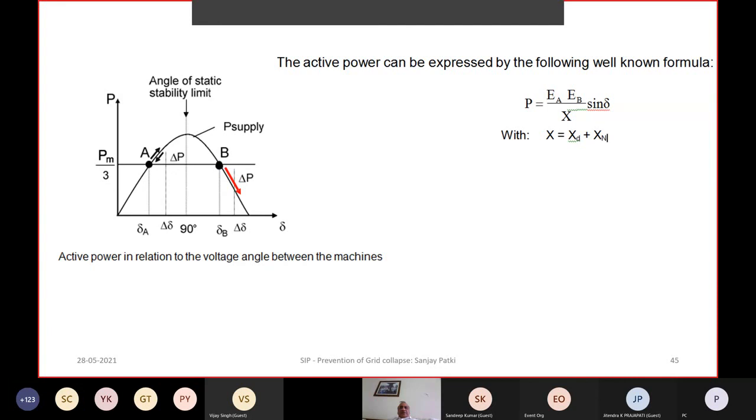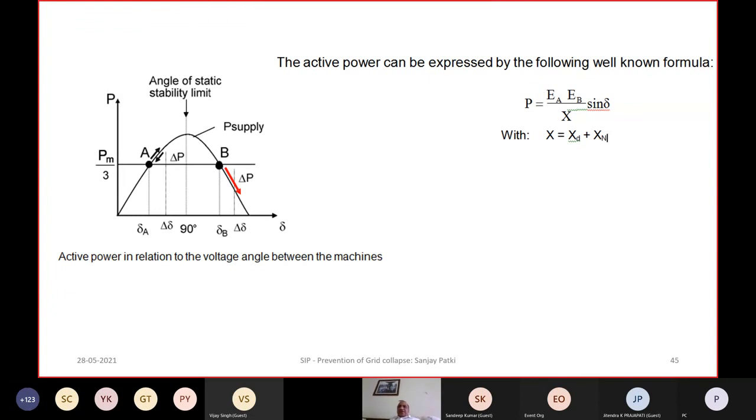At some places, zone 2 is 0.3 second or 0.35 second, and this is basically below the maximum permissible fault clearance time from the stability perspective. Wherever the system clearance time is even lesser, even then you will have to have a protection system in such a way that even a zone 2 situation doesn't arise.